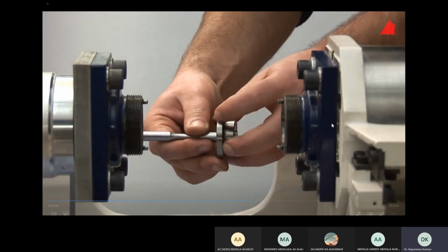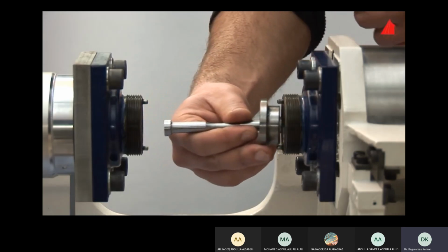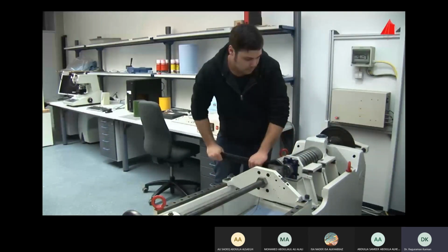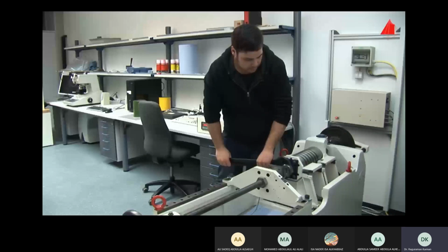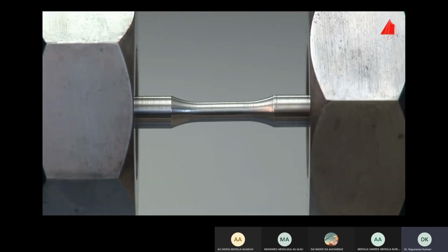For this purpose, the material tester picks the next specimen from his supply and installs it into the fatigue testing machine. He chooses a higher alternating load for the second specimen, a tensile force of 7.5 kilonewtons and a compressive force of 7.5 kilonewtons. Under the increased load, the specimen is only able to withstand 43,600 cycles to failure.